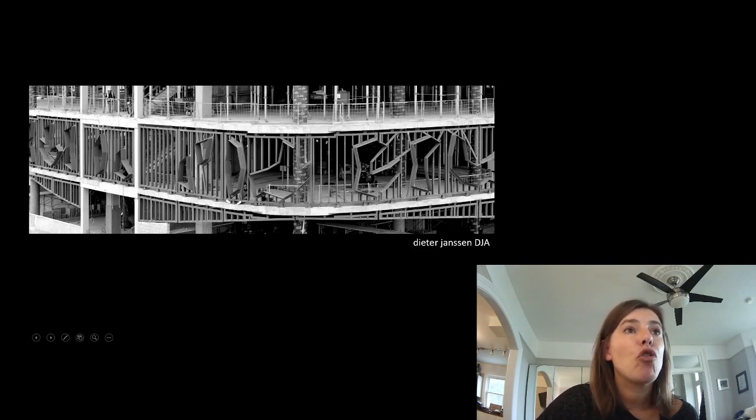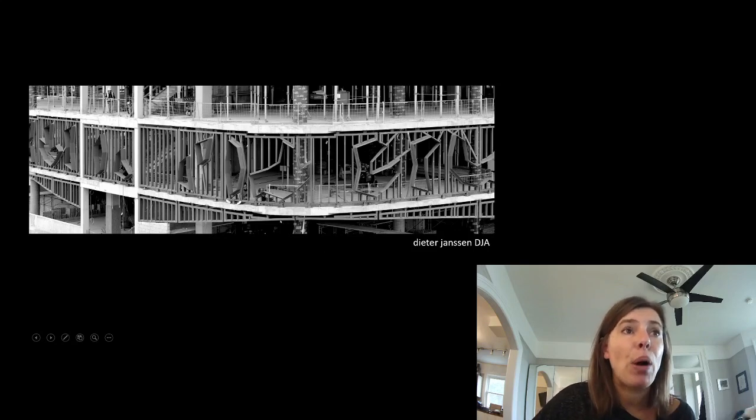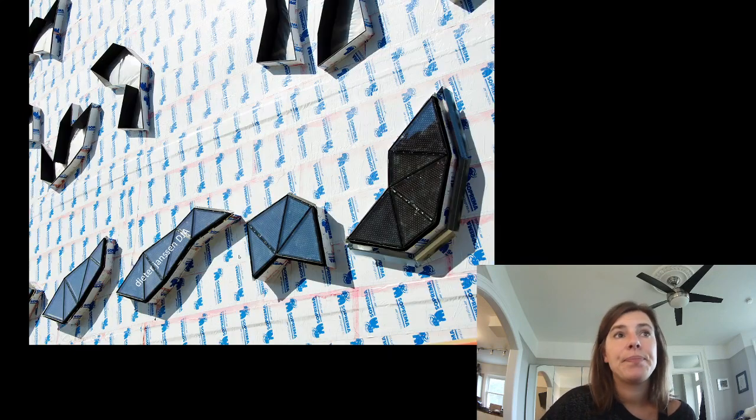You can see we had drop panels that we needed to notch around. There's the element where we didn't actually have a concrete bottom we could connect to, so we had to cantilever down. Here you can see where they're still installing steel on the other side, but over here they've actually installed windows and started putting their facade on.